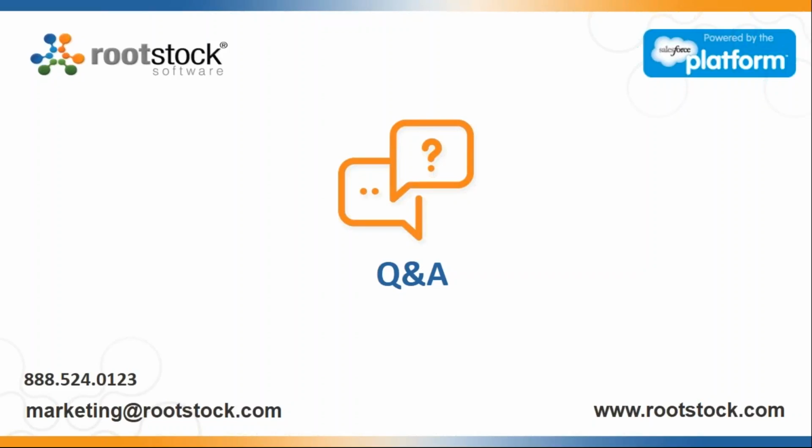Okay, great. And we're going to move on to one more question that just came in. The question is, expanding on your comment regarding when a new part number must be created, are you saying if a part is backwards compatible, although presumably better and preferred, it is acceptable to create a revision of the existing part number? But if the revision is not backwards compatible, then a new part number should be created. Is that correct? That is correct, yes.